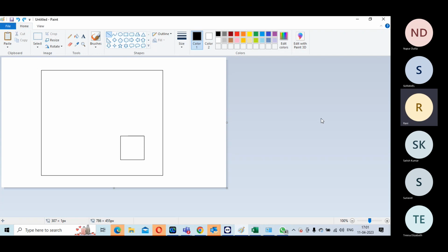What other option? Tell me. We can go for a higher metal layer. What's the option, Satish? We can go for higher metal layer routing. Yes. Let me ask you this question. You go for a higher metal layer and you are expecting the delay to come down. Why? How do you think higher metal layers are going to give you less delay?